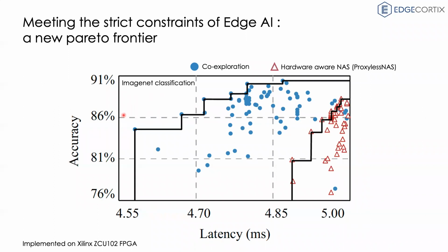And that directly translates into cost savings, as well as matching the performance that you would get from a data center directly on the edge devices. In this case, we are implementing this solution on an edge FPGA, in this case from Xilinx, but you could equivalently use the same design and directly fabricate that into a full ASIC, having satisfied the constraints that you had started off with.